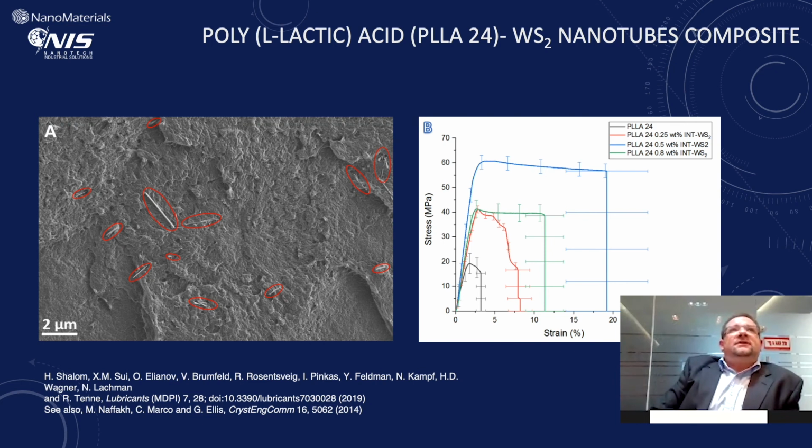the increase of stress withstood by the polymer with this composite material is reached at a moderate concentration of around 0.5%, while higher and lower concentrations achieve lower results. It means that while working with nanomaterials, it is always necessary to find the optimum concentrations required for specific applications. It's kind of the challenge that this combination of academic and industry should always remember.